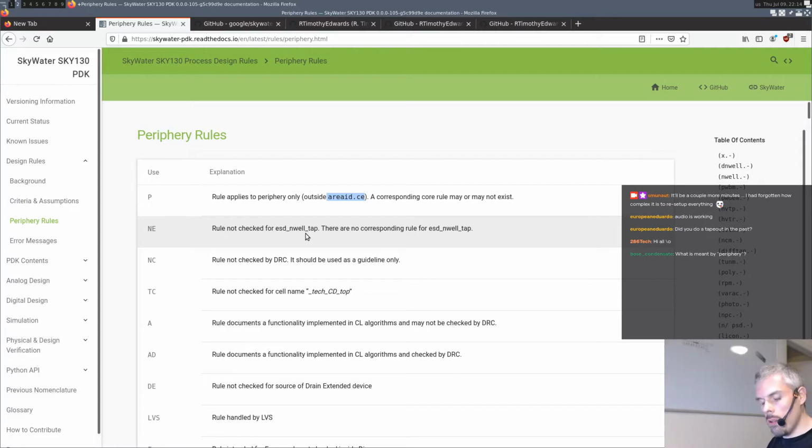So yeah, as I said, the PDK will also contain standard cells. When you synthesize stuff to that process, you don't reinvent the wheel every time. So they provide what's called standard cell libraries, which tell you, if you want a flip-flop, this is exactly how you implement a flip-flop on this process. So you don't have to reinvent it every time, and you can use something that's known working, that has specified behavior and stuff like that. So you don't design every single transistor by hand, basically. And we're going to look at those cell libraries as well.